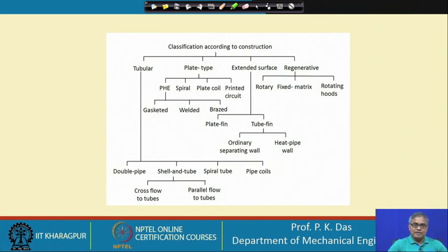The next modification of the double pipe heat exchanger, an improvement for higher capacity, is the shell and tube heat exchanger. So, in this case there is an outer shell just like before, but inside, instead of a single tube, there are a number of tubes. So, through the shell side some fluid passes and through the tube side some other fluid passes. Let me tell you that this is one of the most important heat exchangers because of their number used in the industry.